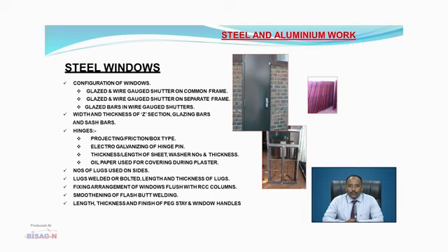Lugs have to be welded or bolted. The length and thickness of these lugs has to be ensured prior to the construction activity. The fixing arrangement of the windows flush with RCC columns has to be in sync and seamless.